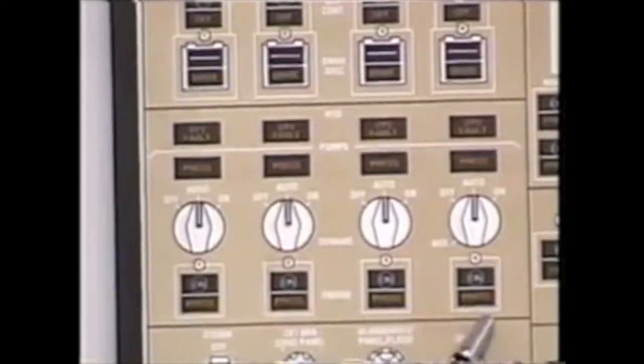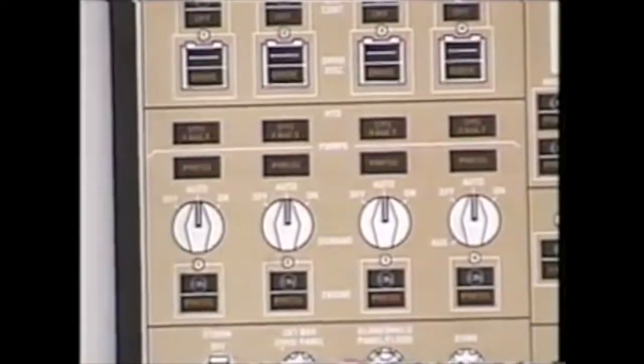The reason we're pressurizing System 4 for the pushback is for primary brakes in a normal brake system. The reason we're pressurizing System 1 for the pushback is for body gear steering with a backup benefit of backing up the brakes.